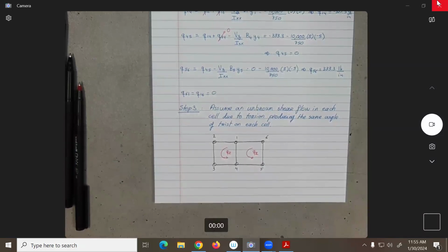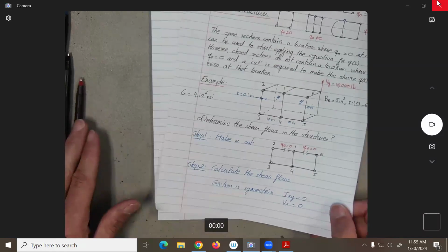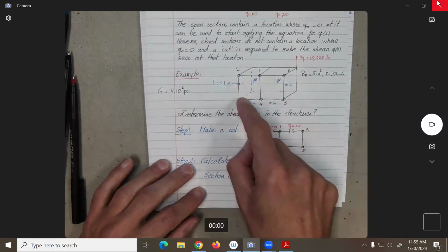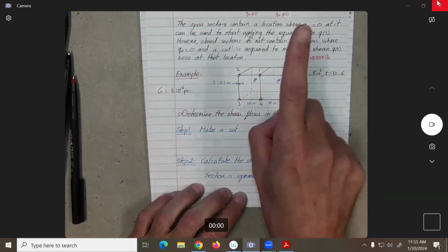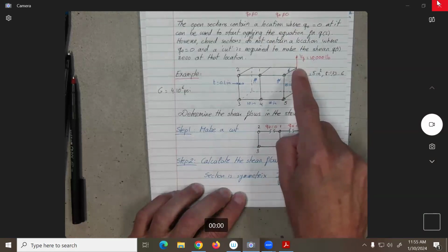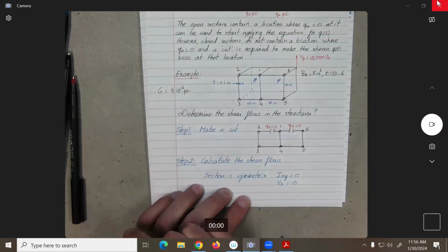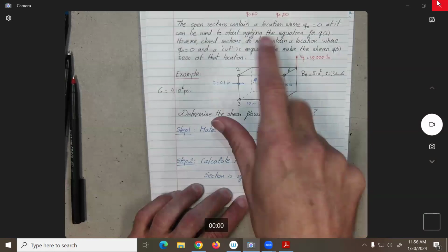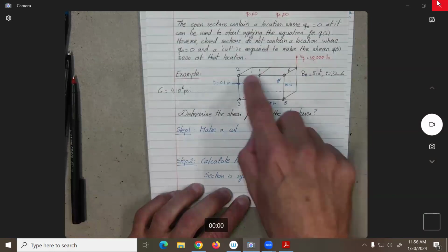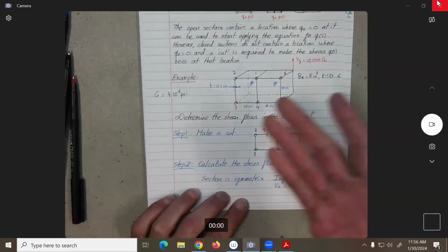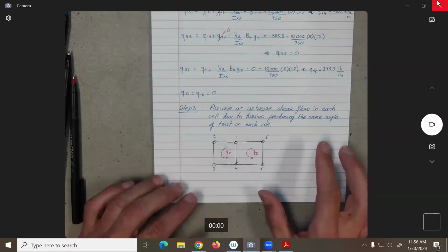Anyway, so let's go back to the problem here, to the initial problem. If you think about it, what type of load will be encountered by this structure? You will have a shear force, no? Remember why? Because Vy is not being applied right at the center, this force is going to produce what into these cells? It's going to produce torsion, no? That torsion needs to be resisted. It should be resisted by shear flows going in the opposite direction of the torsion, no? So that's basically what we're doing. Now, what should be the value of these ones? Well, find out.